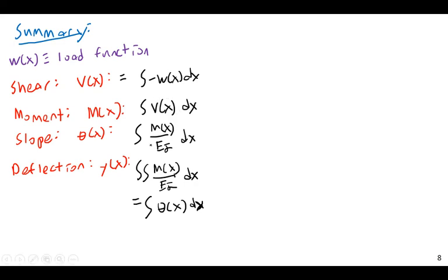But to actually develop the curvature, and the slope and therefore the deflection, you are going to need to know something about the beam. You're going to need to know the cross-section, and you're going to need to know what it's made of. So here, this is statics alone. This you need mechanics of materials. And then finally, I will list these equations have slightly different form on the FE equation packet. What you'll get on the FE exam, you might see a slightly different form.